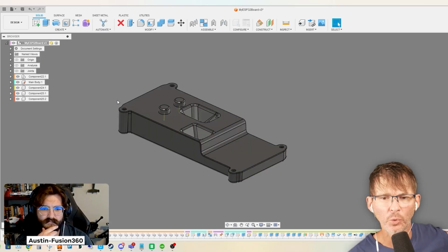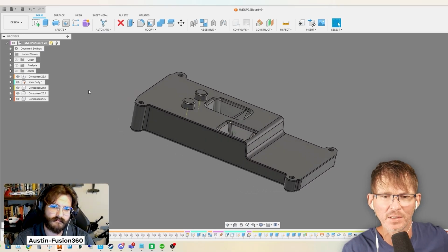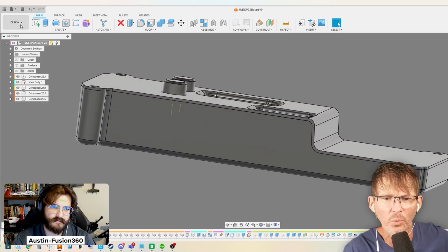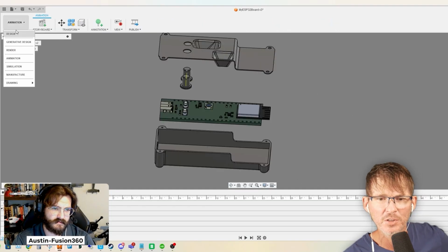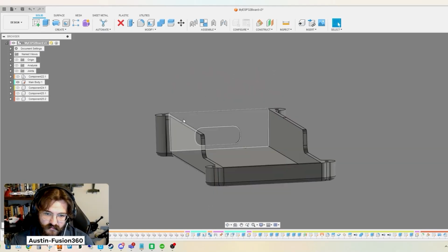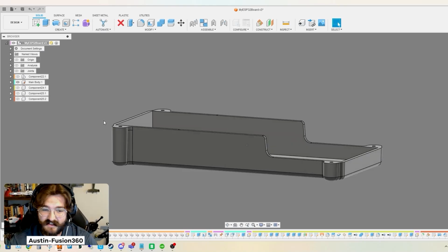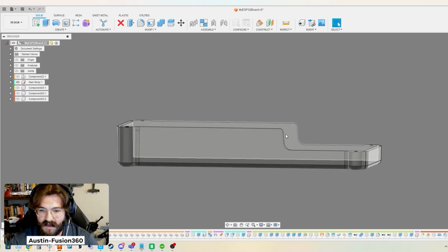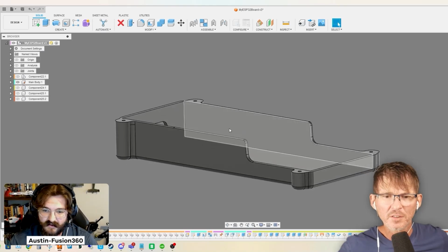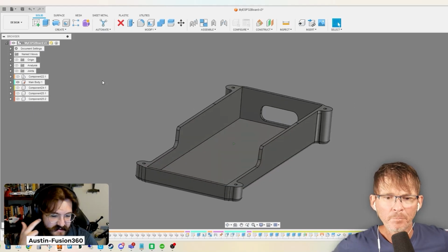Austin, I'm seeing your full enclosure. Where are the 2 pieces? Like your parting line, for instance, is it going to be hidden like it was for Alexander's, or do you have a flat plate, or is it 2 halves? So this part here, I don't even know, correct me if I'm wrong, the parting line could probably match this area here. I think it's almost like Alexander's, where you just have the entire part in one mold. That's what I was going for there.